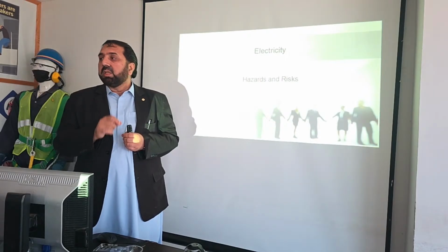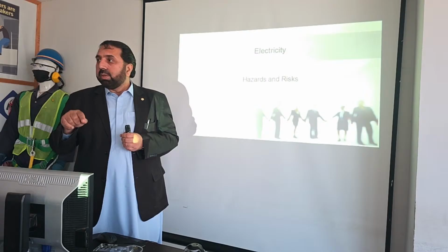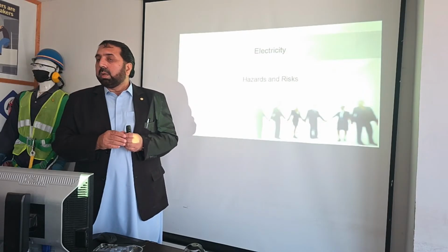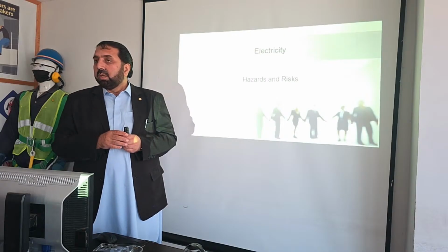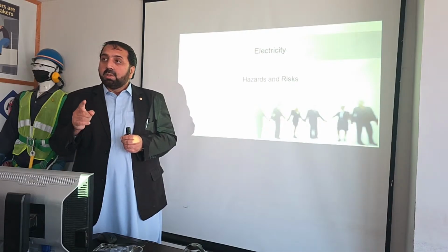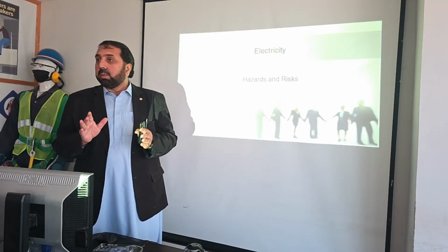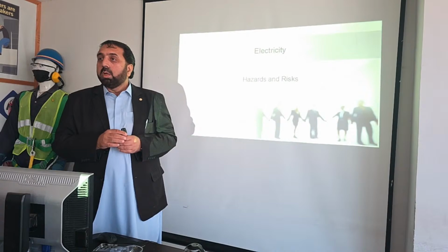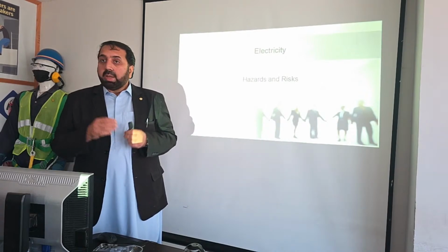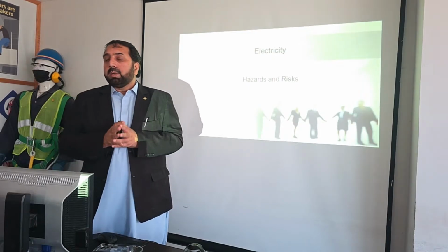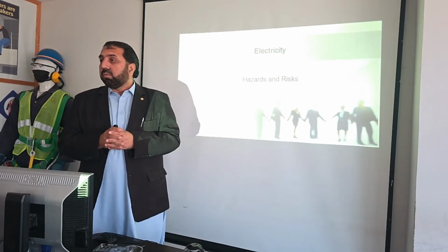So first of all, check the equipment. Then the surrounding area condition. Like if steel is there and the worker is working standing on the steel, or there is a puddle of water, the chances are higher because the conductivity is more. Which is the best conductor in the world? Gold, copper, water, and our human body is also a good conductor. So when the conductivity is more, the chances of the current passing are more.